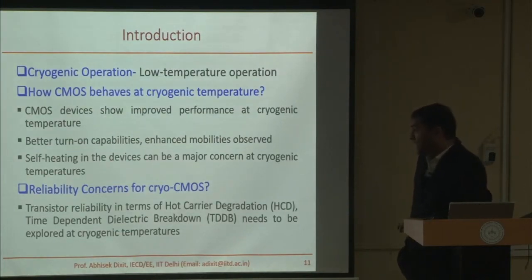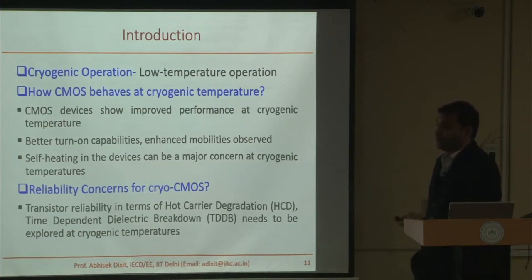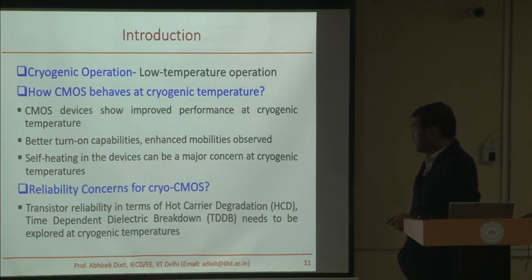There are of course reliability concerns. We have never operated transistors at these kind of temperatures, so we don't know how transistors will operate, how the reliability, things like hot carrier. So basically we want to look at everything in the cryogenic regime and make sure that it works the way it was working at room temperature operation.